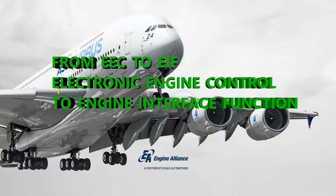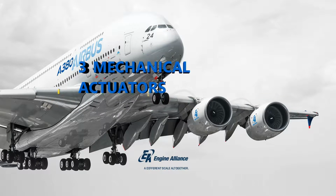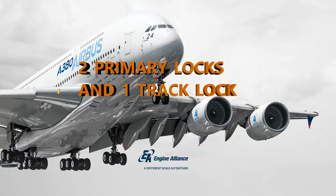Now, what about components? I mentioned the cowls, but remember I said you've got actuators. There are 3 actuators that are connected to an electric motor, and that's per engine. And there's the locks. How many locks are there on the translating sleeves? There are 2 primary and 1 track lock. So 2 primary locks and 1 track lock.